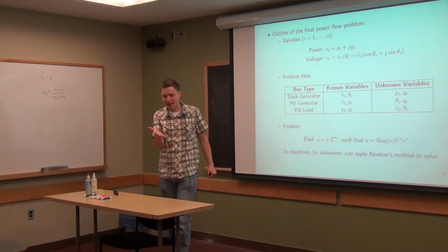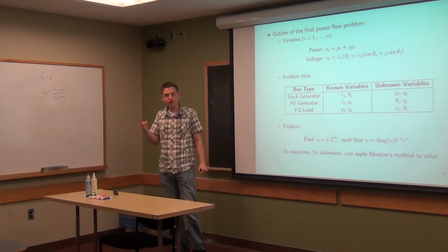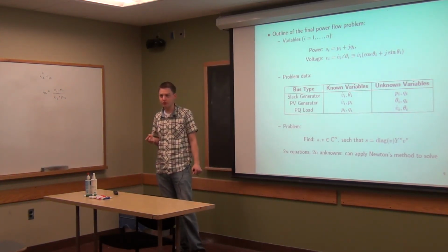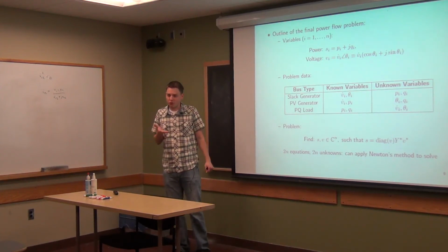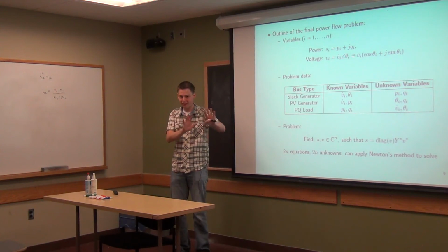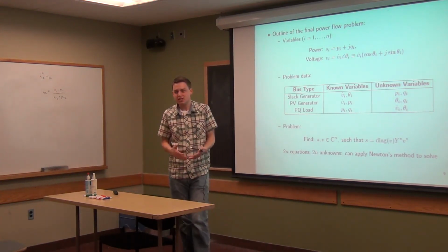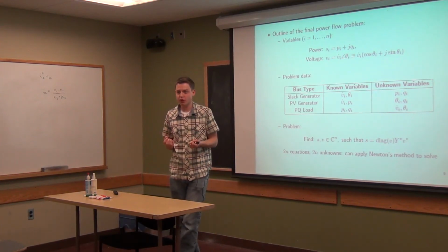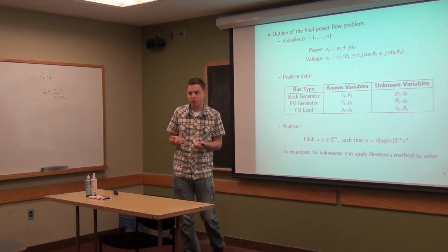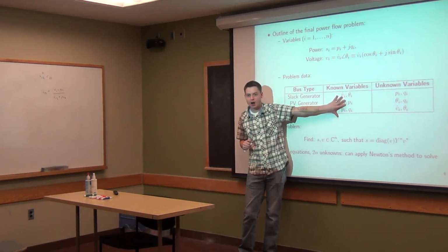To counteract that, the generators will, of course, have a very tight control loop that maintains their rotational frequency. So what really happens is that everyone works together in some way, depending on how all those control loops interact, to pick up the slack all together, each one just trying to maintain their own frequency. That's what really happens. And so it's really unknown in practice exactly how each of these will do it.